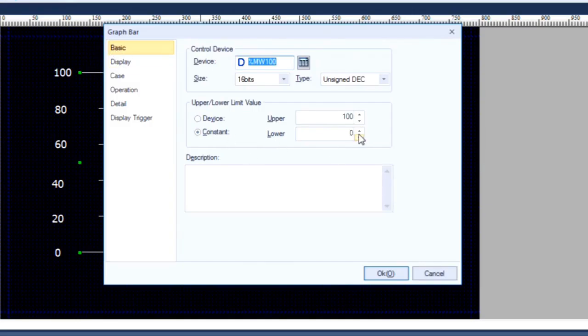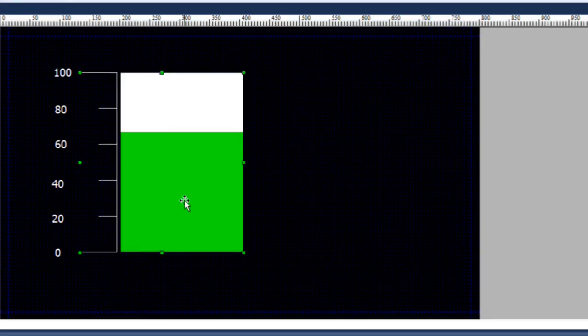mode, essentially meaning it stays steady from 0 to 100. We just need an MW100, and if you give it a value, our graph will change. Now, we can read this MW100 value from the PLC and use it in that process. When the MW100 value changes, this graph also changes for us on the HMI. All right, since we want to test this together here, that's why I'm going to do it myself.